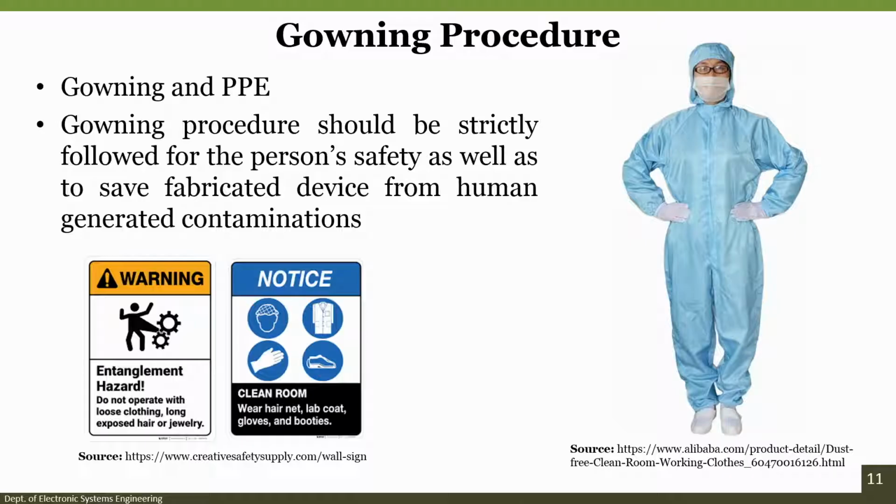Also, if you have loose clothes, there is an entanglement hazard. So, you need to wear hairnet, lab coat, gloves and booties or shoe covers inside the clean room.